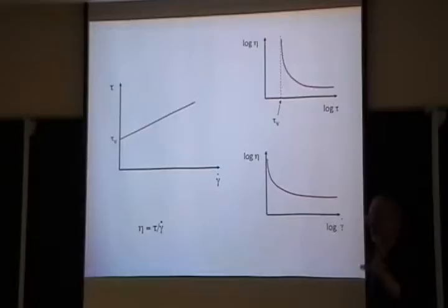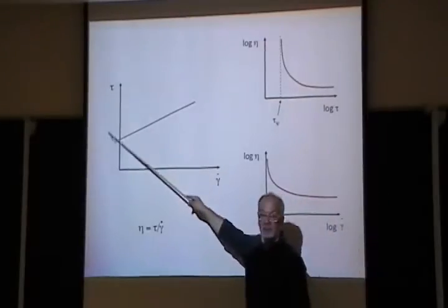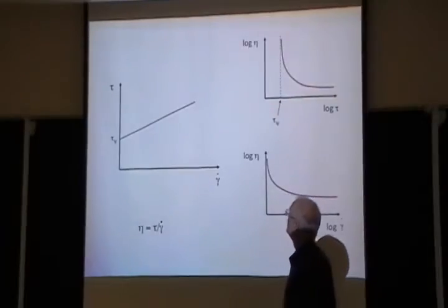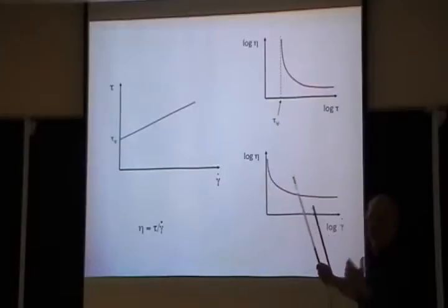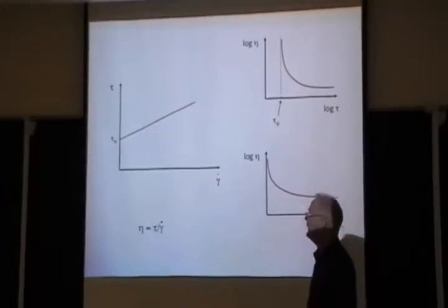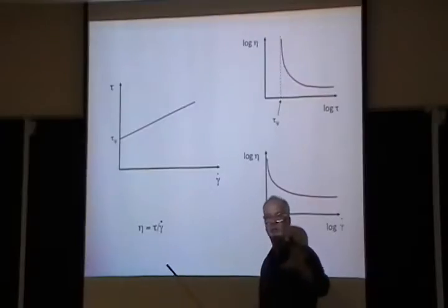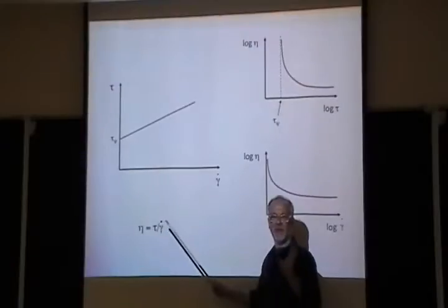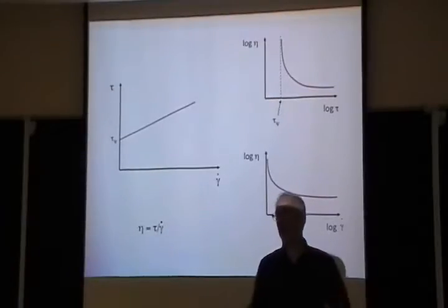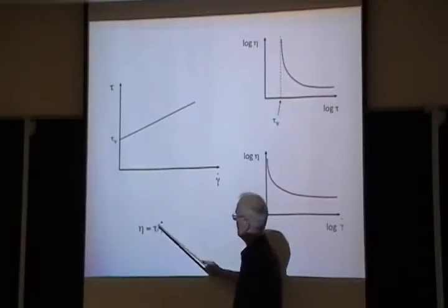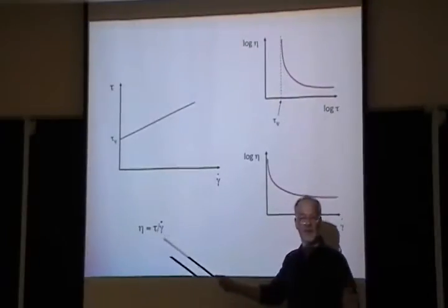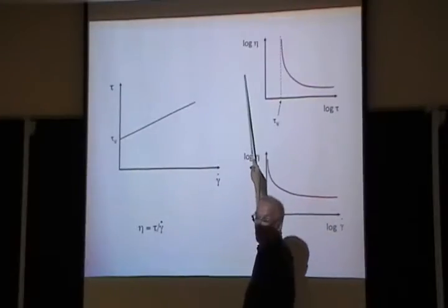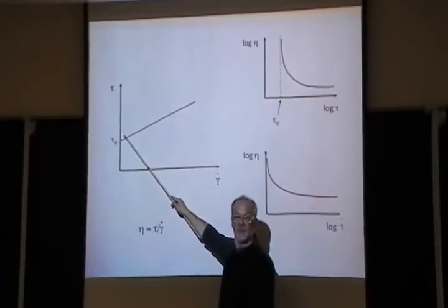And so I just want to get you familiar with this notation. So if you have a linear thing like this, right, that was an offset, and now you plot it down on a log scale, let's say here. First of all, what you want to plot is the viscosity. And the viscosity, in my way of thinking about it, is totally silly and simple: the ratio. So no derivative, no nothing. I'm defining it in the standard practitioner's way. You measure the stress, you set a shear rate, you divide through, and that's the viscosity. It's very simple. If you take something like this, of course out here you get your eta, but up here things happen, right, because of this offset.